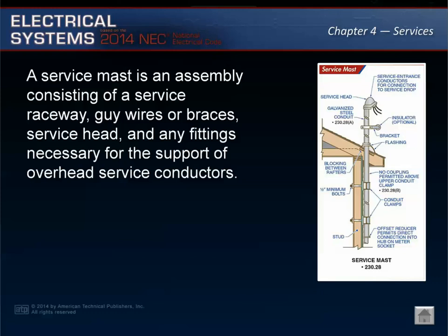A service mast is an assembly consisting of a service raceway, guy wires or braces, service head, and any fittings necessary for the support of overhead service conductors. Service masts must be designed to support the weight of the overhead service conductors under varying conditions, including those when snow and ice may add additional weight to the conductor span.